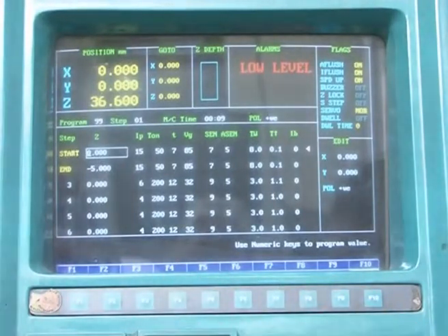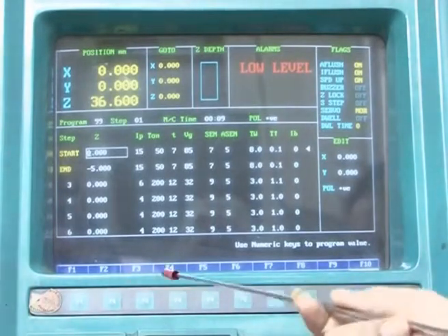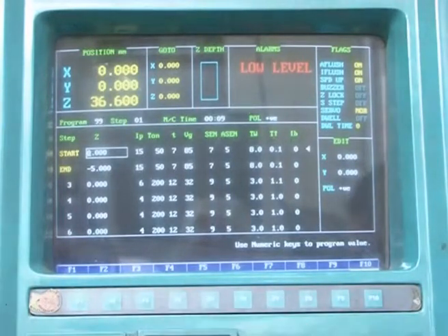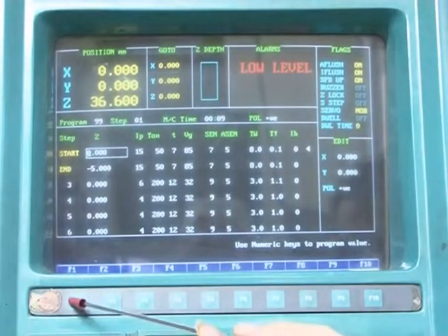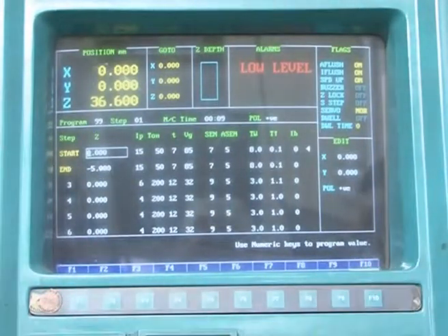Auto position means once you get some particular distance between the workpiece and tool, after that you press this auto position so that the workpiece and tool get set automatically. There is no need to give an extra motion. Hold means once you give a machining operation, suppose you want to stop the machine at a particular moment, then you press hold, then machining will cease. And spark means machining starting time. When you press the F1 button, then machining starts.